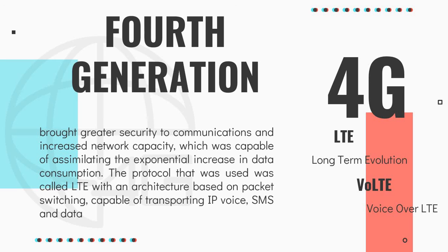The 4G uses the LTE network. LTE is Long-Term Evolution, the first generation of mobile telephony with a radical change, being different from the second and third generation technologies. It uses orthogonal frequency division multiplexing, a technology used earlier and conceptually simpler. It has high spectral efficiency, high data transmission rate, short round trip time, and flexibility in frequency allocation. And the other is VoLTE, voice over LTE.